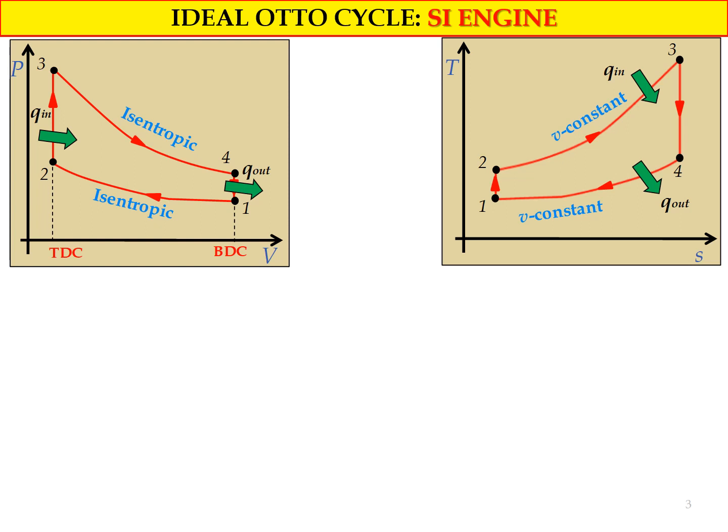Okay, if you look at the TS diagram, from state 1 to state 2, the temperature increases from T1 to T2, and because the process is isentropic, the value of S2 is equal to S1.